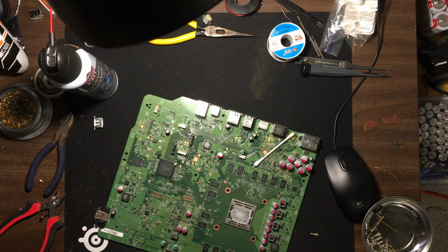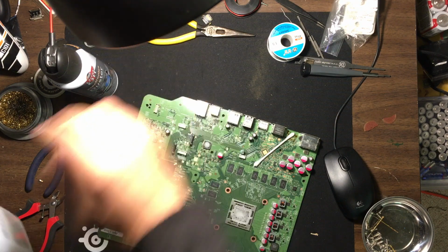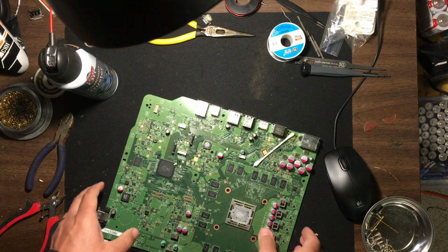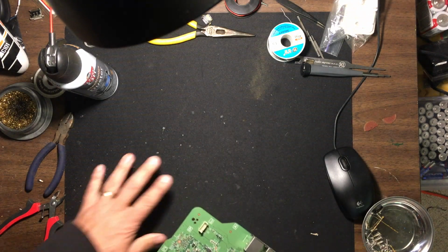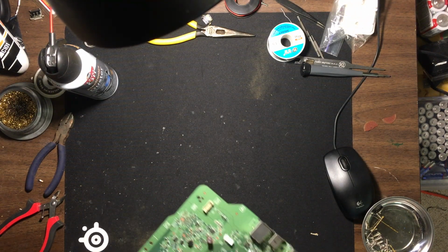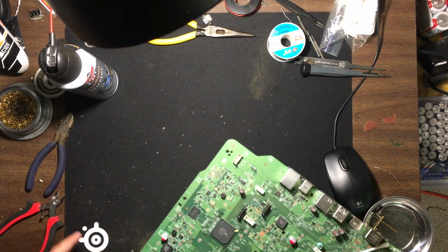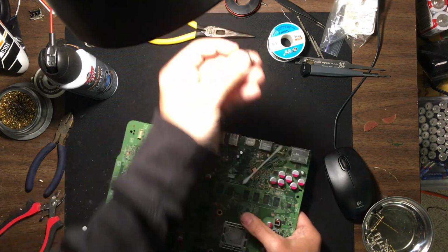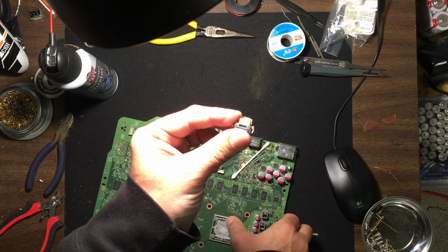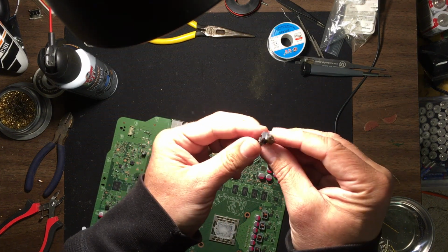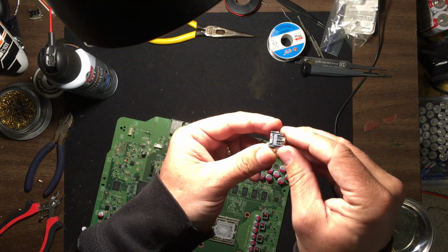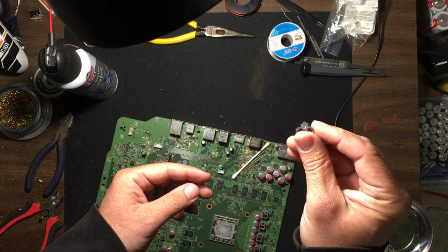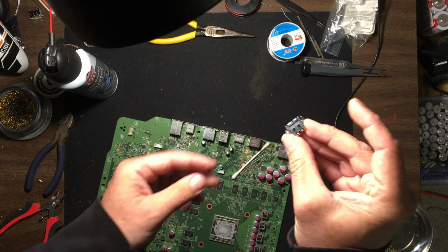Clean up my workspace because I have dust everywhere, and get ready to actually solder down the new port. I've got to clean up my pad here. It's just a mess. You can see all the dust and stuff from cutting. This is what the port looks like now that it's been cut off. The entire top metal's off. I basically eventually cut the legs off, pushed it down, and you can still see this is low melt solder still on those pins there. But there you go, that's the old port.